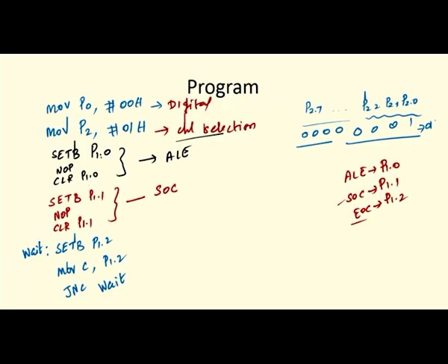Okay. So, what does it represent? I have activated the EOC signal, which is continuously high, right. Whenever the bit is set, it goes low, and during that time it will exit from the loop. So for that we are giving: if there is no carry, meaning it is not set, then we repeat the process. Once it is set, we exit.